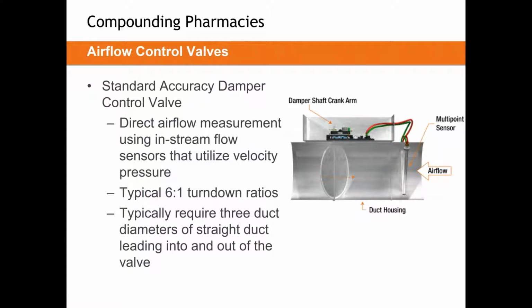Some of the defining features of a VAV box are that they measure flow, and they usually measure that flow invasively in that airstream. So you can see we would often have a multi-point sensor in that airstream, capturing airflow, gathering an idea of what the velocity and total pressures are, and calculating an airflow from that.